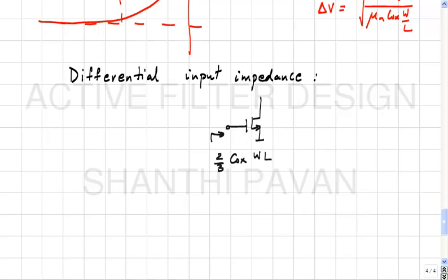Why I am emphasizing this is that when we go further, you will see we have all sorts of transconductors where the DC input impedance is high, sure enough, but as frequency increases, the input impedance is not as clean as a capacitor. It's got inductive components and negative resistive components and so on, which sometimes becomes problematic, which is why I'm bringing this to your attention. The other thing is the finite output resistance of the device. Okay. So what will be the DC gain of the transconductor?